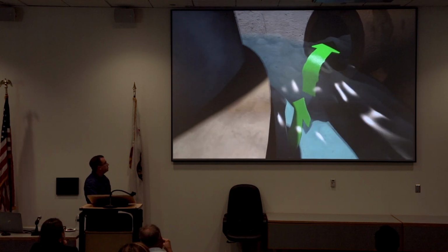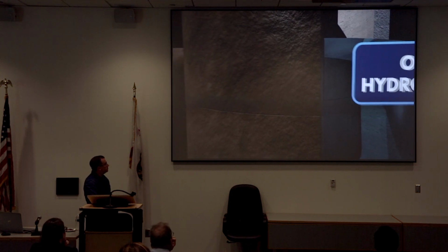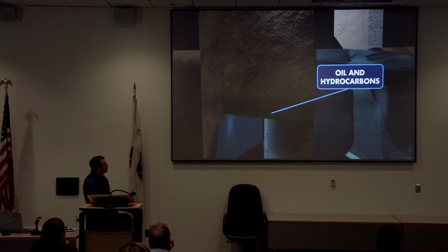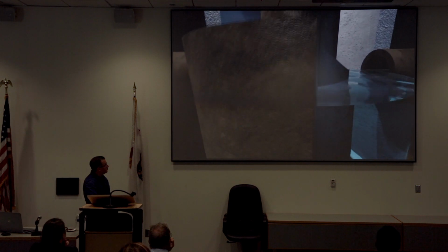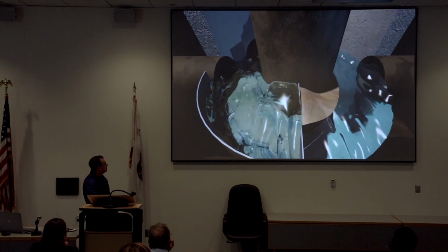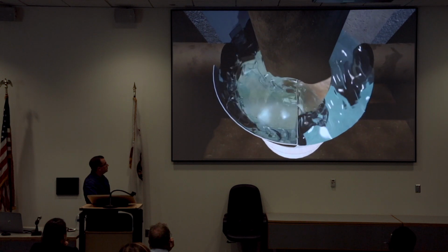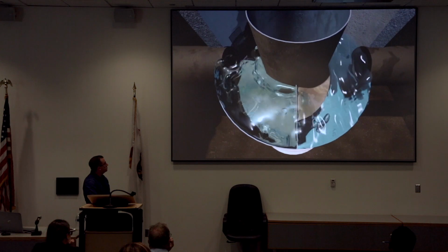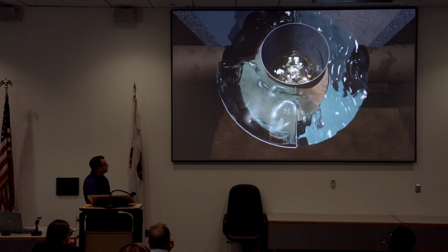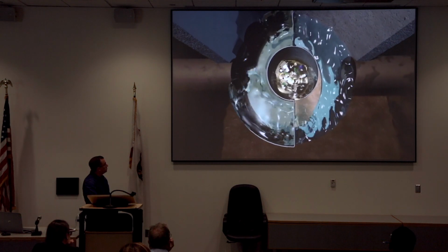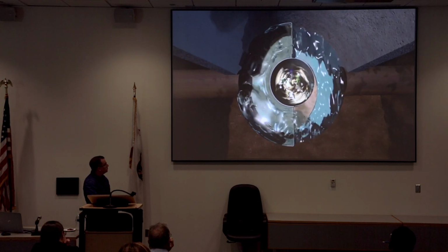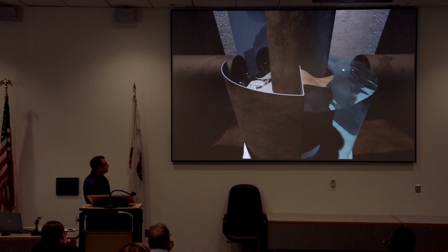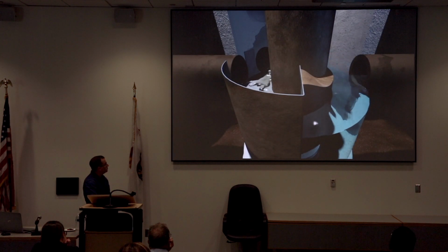The baffle acts as a wall for hydrocarbon containment and prevents agitation of hydrocarbons when high flows spill over the diversion weir. During high-intensity events, the internal diversion weir directs flows greater than the design storm around the treatment chamber. The treatment capacity of the system is not diminished during high-intensity events. The design of the system ensures settled material captured in the sump does not escape, and floatables cannot wash out of the separation cylinder. When the storm event ends, the water surface is returned to the outlet pipe elevation.